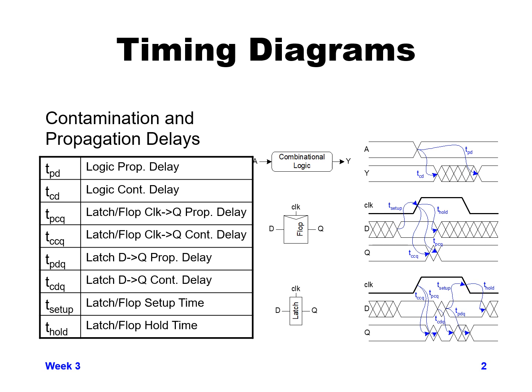Then there's also, as we've talked about before, the combinational logic contamination delay. This is the shortest amount of time it can take to get through the logic. There's an arrow from when A switches to when the output switches, and that is a lot earlier than the propagation delay.